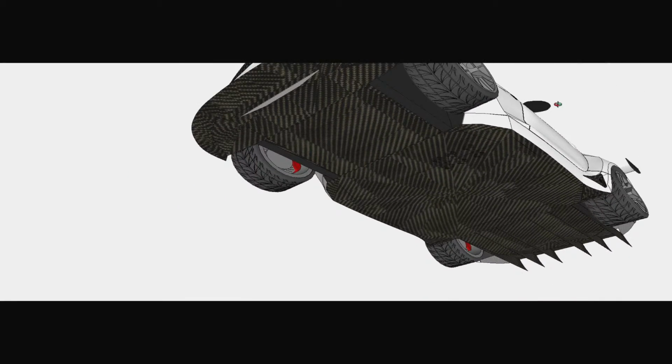The undertray is a tray that covers the undersurface of the vehicle, and besides clearly being for protection purposes, it also allows the vehicle to have less upward force acting on it from the air by covering all the crevices and nooks and crannies created by the positioning of the flooring of the car and the drivetrain and the drive shaft and the differentials and the suspension. So basically it creates a flat surface and it minimizes the upward forces to make the car more stable.